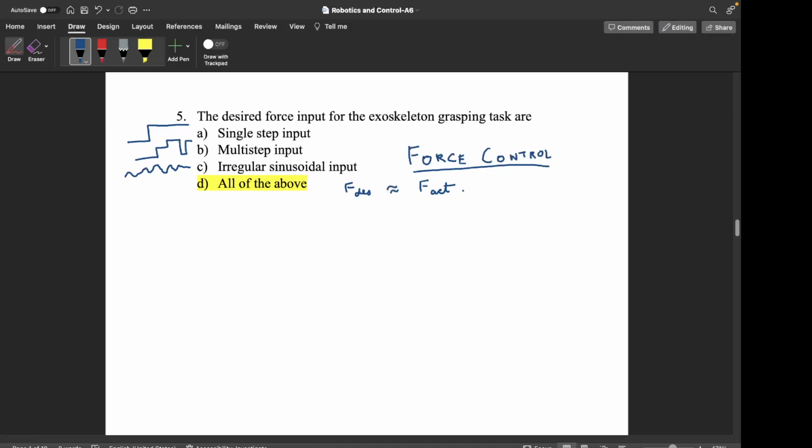And for this you would imagine that, okay, you have seen in position control and velocity control, right? Similarly we have now here force control. There you would apply some feedback based on gains multiplied with the error. Whenever we want to control something using feedback, we find the error between the desired and the actual, then multiply it with a certain gain parameter, and then use it to decide the correction, like whether you need to increase or decrease the force.